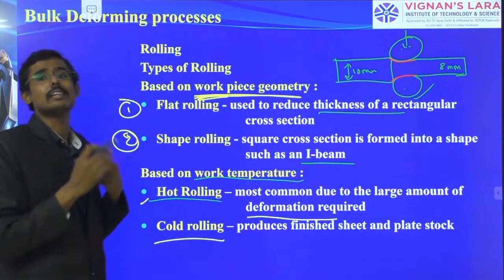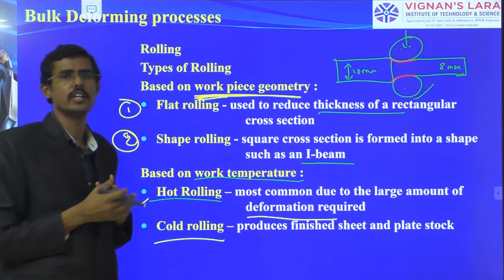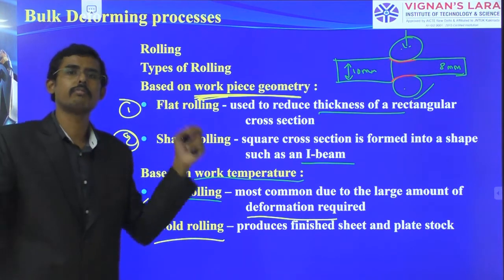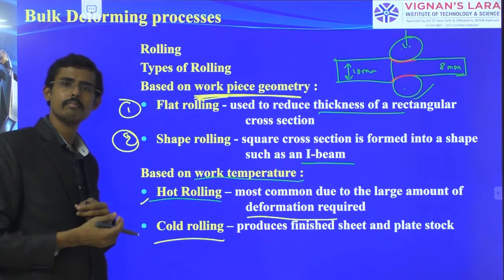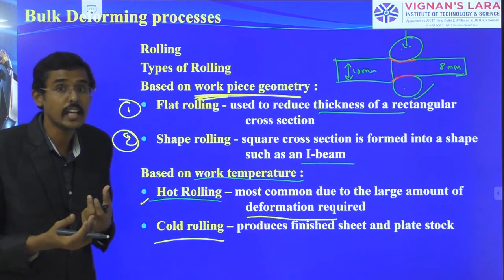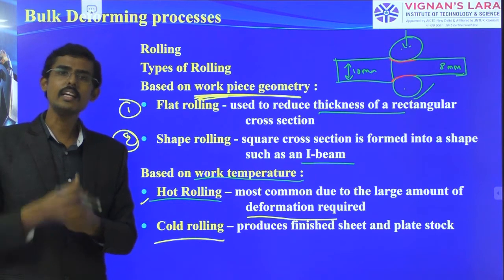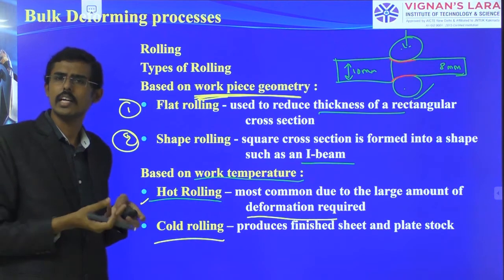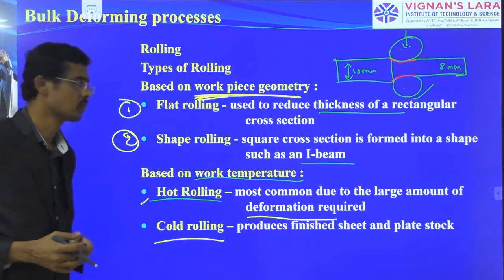Now the thickness is increased. I can't give more force, so more loads are needed. Machine setup will become large. At that condition, I am just heating, and the material becomes readily deformable. The word I am using is readily deformable. And then when we press, forces are given, it is a little more convenient to change the shape. That is why hot rolling and cold rolling.